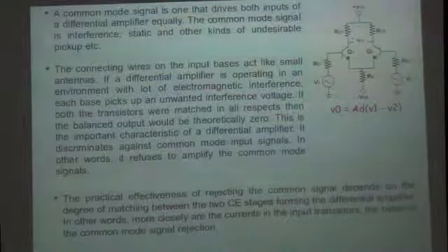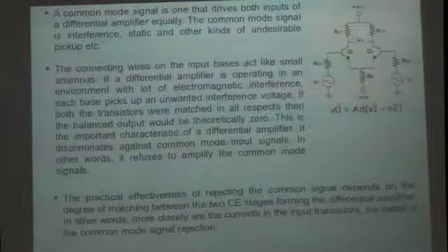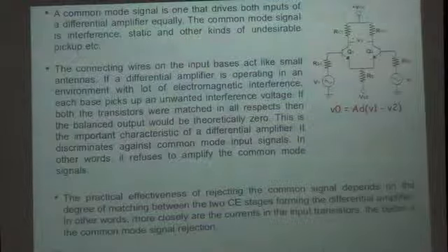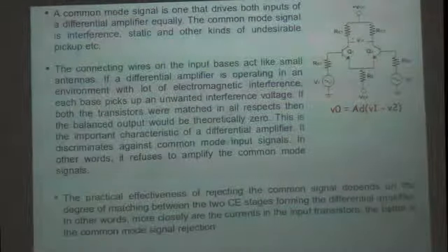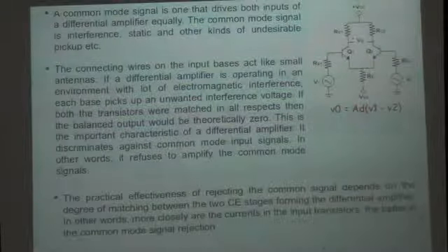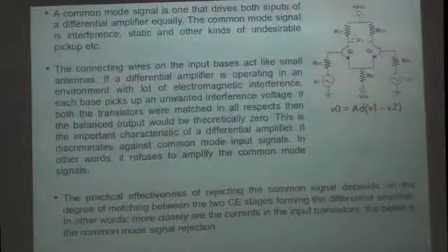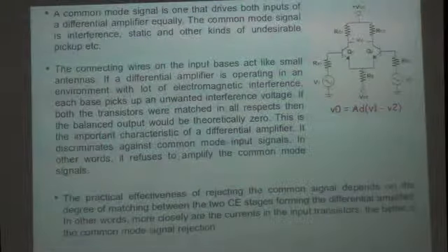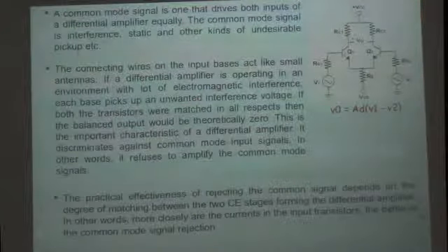Normally, if you design a difference amplifier by making use of two transistors, they are the same in all respects. But VBE of one transistor is not equal to VBE of the other. So even if V1 and V2 are both the same, because if you look at this equation theoretically, if V1 and V2 are both the same, the value of VO must be equal to 0.